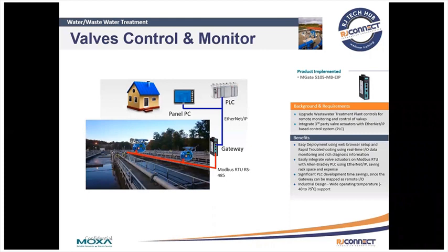Another typical application, especially in South Africa as well, is a valve control system where the valves are Modbus RTU, but the existing PLC control system is Ethernet/IP based. Easy and rapid deployment using web browser setup. Easy to integrate valve actuators on Modbus RTU with Allen-Bradley systems, saving rack space and expense, and significant PLC development time savings since the gateway can be mapped as a remote I/O device in the PLC programming software.